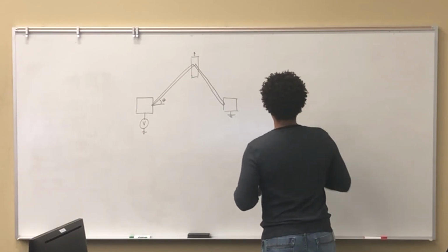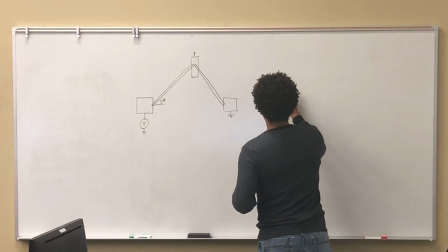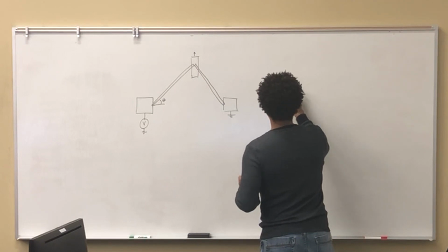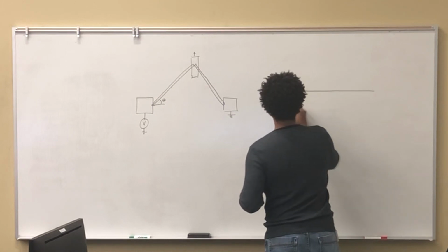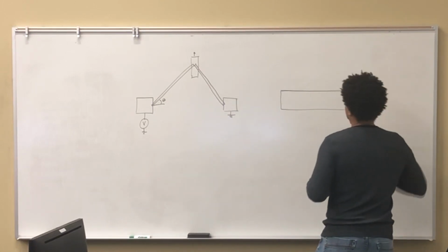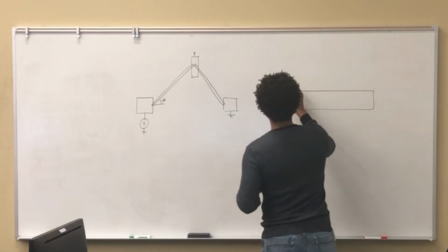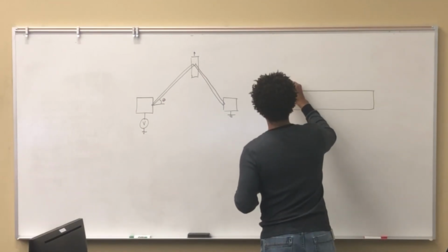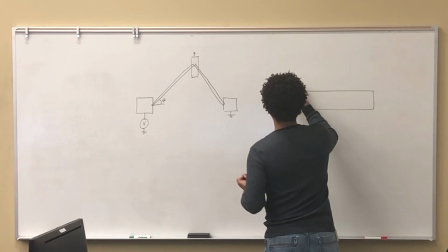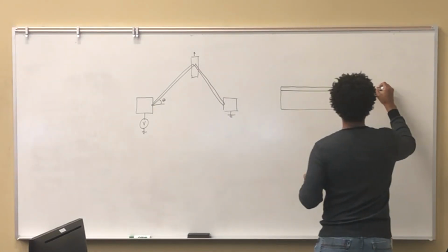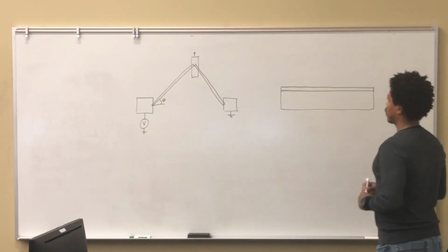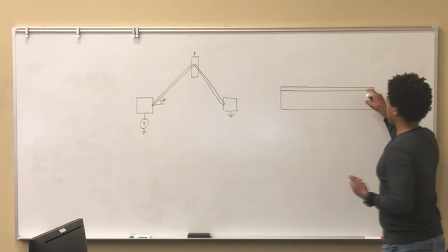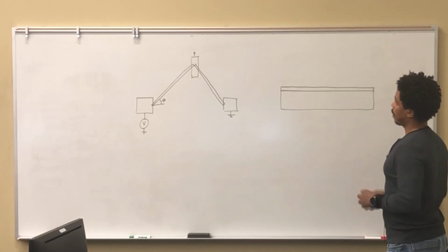So basically, and we talked about this a little bit before, how things are made at the microscale, where you have a substrate, typically silicon. Okay, and then what you do is you deposit through all kinds of ways. It could be chemical vapor deposition, or what have you, or you could spin on some sol gel, or just various ways. There are various ways to put on different layers at a time.